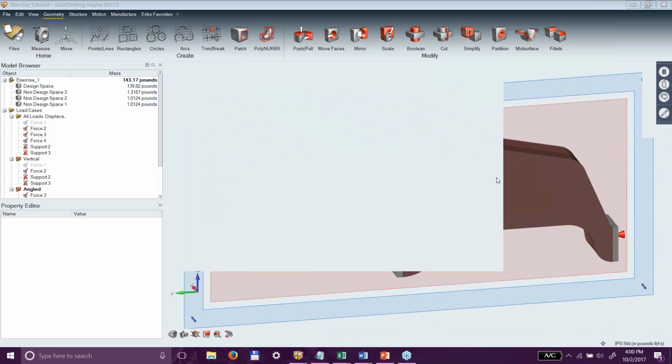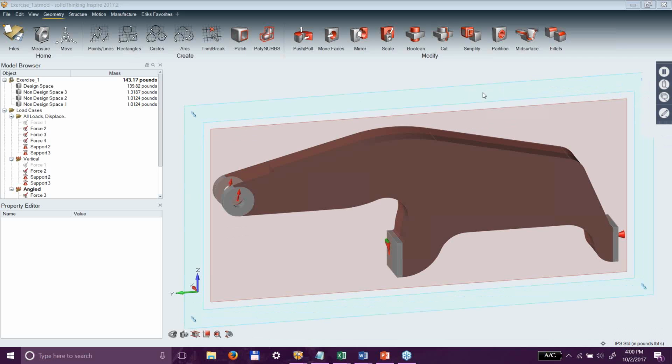And was it only modeled in Inspire and not OptiStruct? Were they happy with the results with only Inspire? Oh yeah, that's why they put it in space. I guarantee you they would not have put it in space if they weren't happy with the results. And just to add to the element type, for the plate model, since you're showing mostly solids: for plates you can choose trias or quads for your element type.